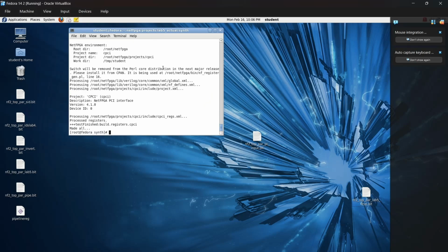So yeah, we are able to do a synthesis. I actually did a synthesis earlier and kept a bit file over here. We tried implementing this on NetFPGA, but we just weren't able to track the outputs in time. It was too fast, with the whole process finishing in 7 clock cycles, so it was hard for us to track. So we just went with the other approach of giving an input PC and implementing it.